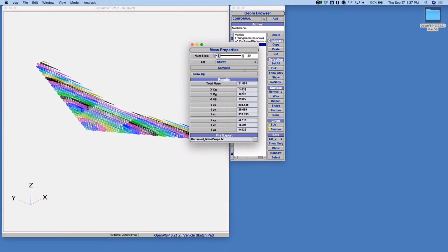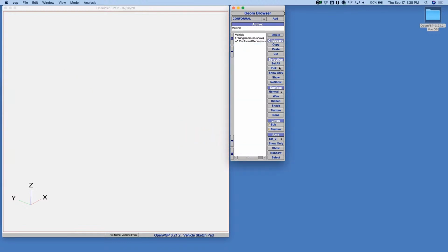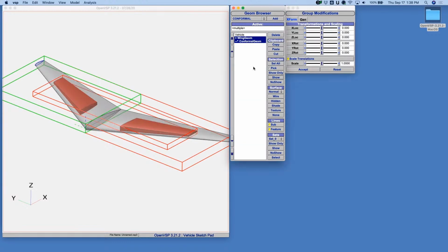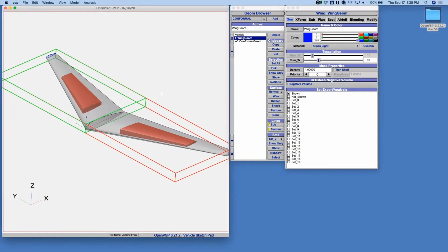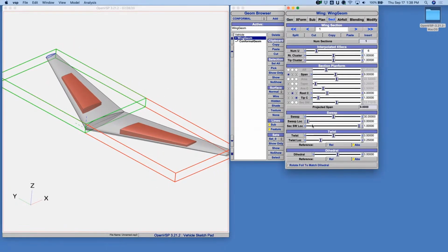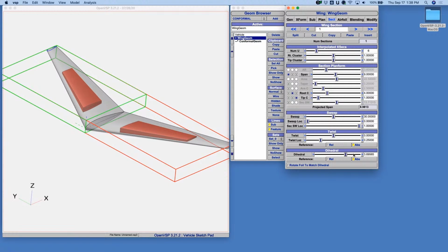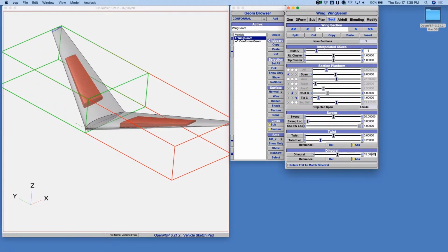I've actually developed an algorithm to look at fuel tank mass, moments of inertia, and CG location as it fills from empty to full. So if you have some really strangely shaped fuel tank, especially say a wing with dihedral and sweep, if we come in here and we want to show all these again, if we come in and we put in a bunch of dihedral, we'll say, right? So let's crank it up 15 degrees of dihedral.